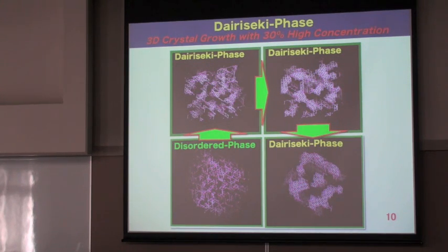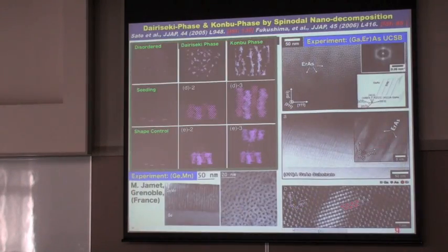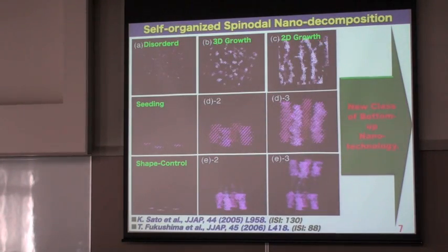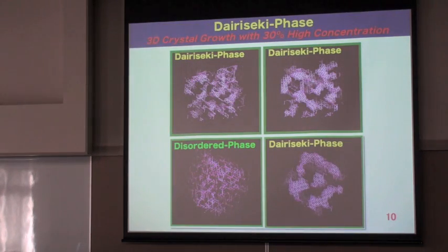And we are using this kind of spinodal decomposition in order to make a high efficiency photovoltaic solar cell. You can mix the 2 kinds of semiconductor. This is a type 1. This part is a type 2, type 1 band gap alignment. So electrons run this way, holes run this way. So you can completely separate the electron and hole. And also using this kind of nanowire, you can use some discrete energy levels in order to realize multi-exciton formation using the inverse Auger effect. So that's a different story altogether.